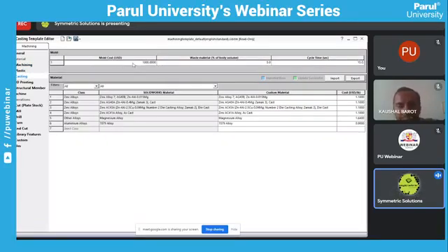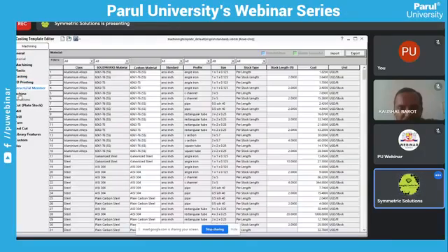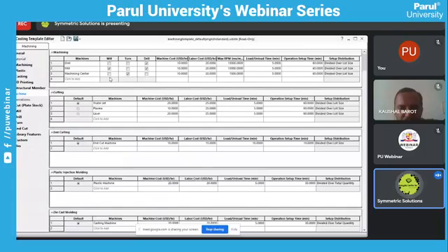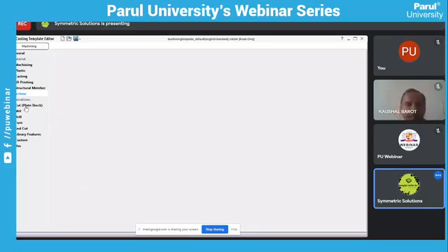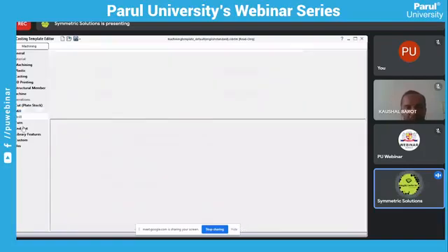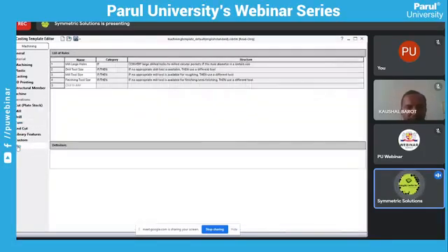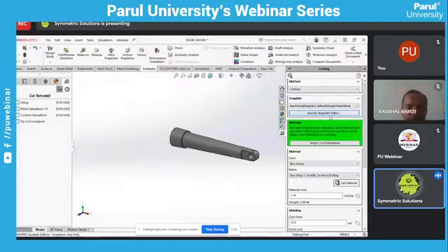Now casting, apply your mold cost, then waste material percentage and cycle time. This is the material costing. Then machining, drilling, milling, machine centers, apply your machine time, loading, unloading time, labor cost, setup time. Then cutting, end cutting, plastic injection molding, die cast molding, apply your costing as well as timing. Then operations: cut, milling, drilling, turning. And finally rules, terms and conditions for costing. Fine. So this is the cost editor for this costing template.